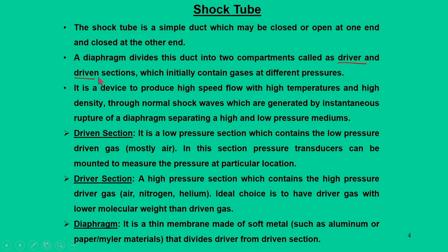Giving more details about the driven section, it is a low pressure region which contains the driven gas, mostly air or any test gas, and in this section there are many measuring instruments. The pressure measuring instruments we call pressure transducers, because these are dynamic phenomena, and these measurements can be done at particular locations.